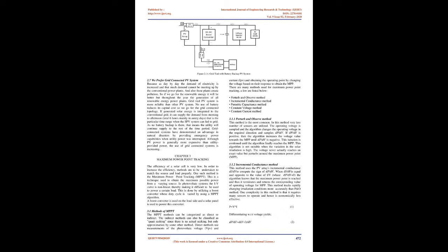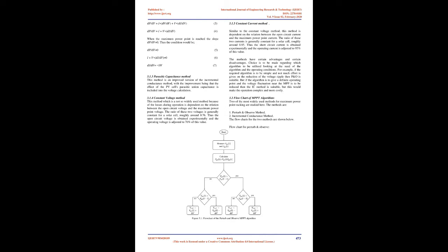Thin film PV is made by depositing an ultra-thin layer of photovoltaic material onto a substrate. The most common type of thin film PV is made from the material ASI, amorphous silicon, but numerous other materials such as CIGS, copper indium gallium diselenide, CIS, copper indium selenide, CdTe, cadmium telluride, dye-sensitized cells, and organic solar cells are also possible.